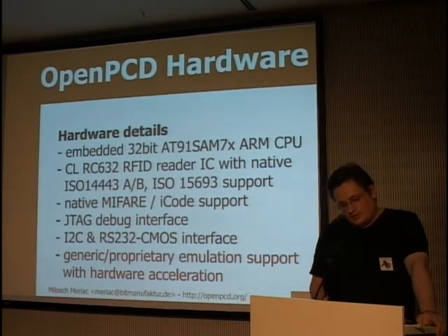The disadvantage of this card is that the cryptography algorithm behind it is not documented at all. So currently there is no possibility to talk to such cards unless you use the RFID reader ICs provided by the very same manufacturer that manufactures the tags themselves, in this case NXP. So basically we only use this for providing MIFARE support, and I think this is inevitable if you want to have an RFID reader.